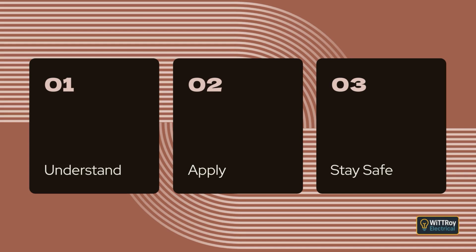Clause 2.6.2.4 Arrangement. Clause 2.6.2.4 explains how final subcircuits must be arranged when additional RCD protection is required. The rules are simple. In any installation with more than one RCD and more than one lighting circuit, the lighting circuits must be shared between the RCDs.